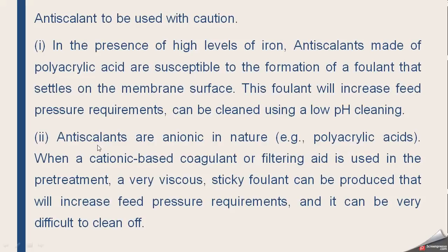And antiscalants are anionic in nature, that is polyacrylic acid. When a cation-based coagulant or filtering aid is used in the pre-treatment, a very viscous, sticky foulant can be produced that will increase the feed pressure requirement, and it is very difficult to clean off. So when we are using some coagulant or flocculation agent before the treatment, then due to the presence of this coagulant, the antiscalant will interact with it and form a sticky material which will stick on the membrane surfaces, and it is difficult to remove that material.